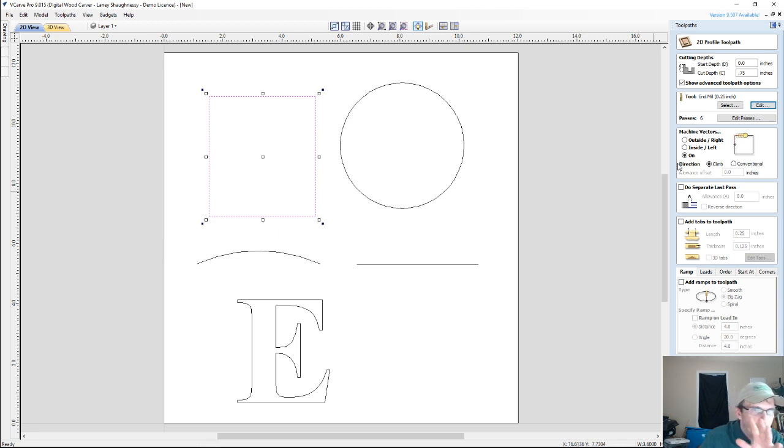Now, aside from that, if I were cutting on the outside of the line here, when that toolpath starts, it's going to plunge down to the first pass depth, and it's going to go around the part, and then at its starting point, it's going to plunge down again, and continue plunging at that same spot, and that will end up leaving witness lines on our cut.